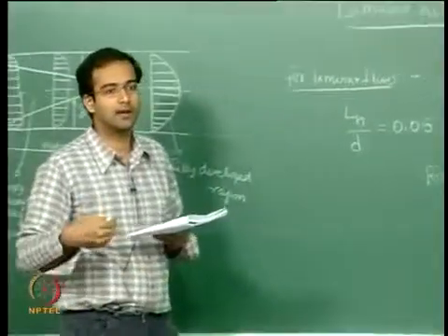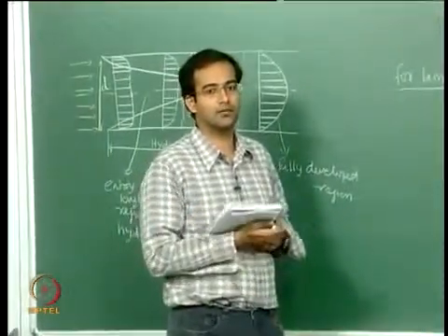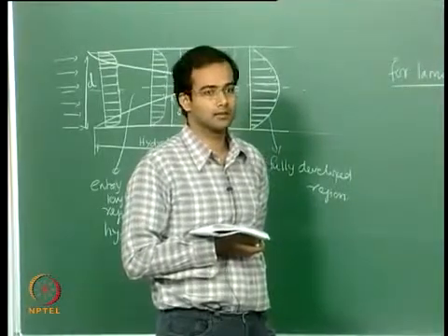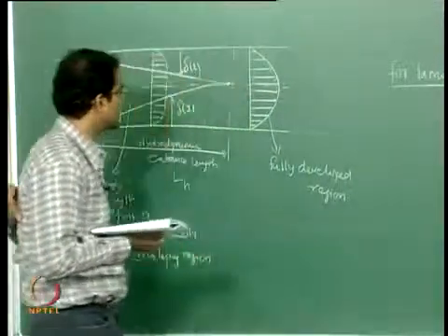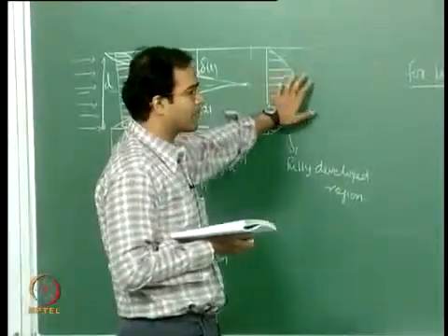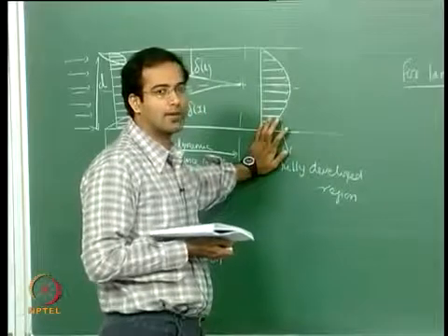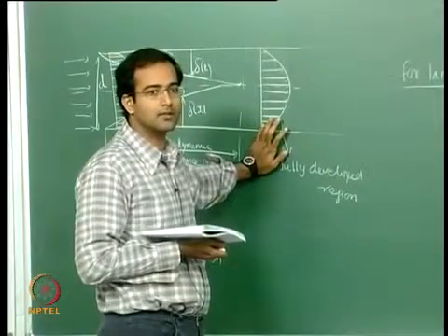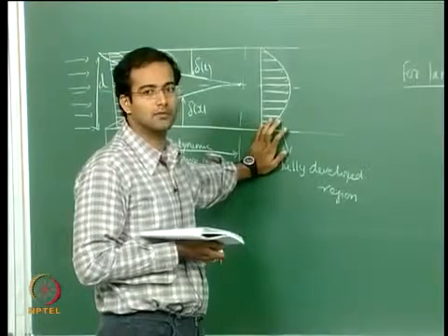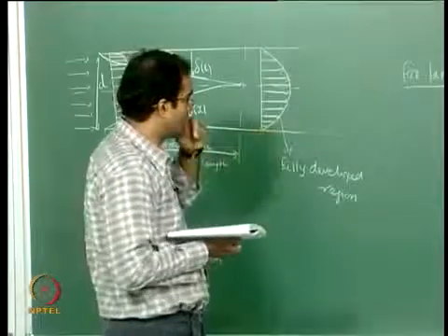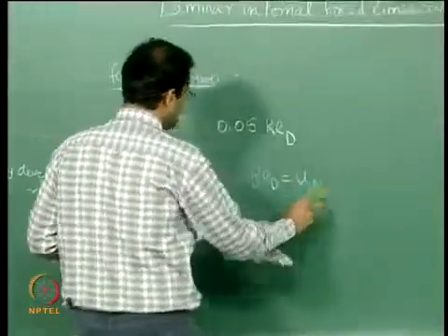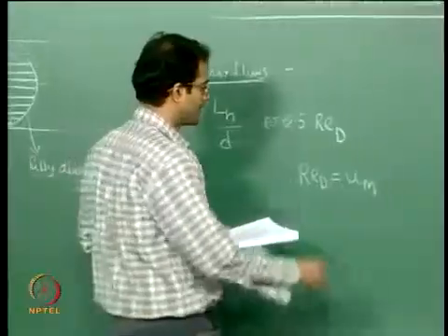so what kind of characteristic velocity do we have to use? That is the question. So the kind of an average, because here you see, even if you look at a fully developed case, you have a profile which is a function of y. Okay, so you don't have a fixed velocity value like in the case of external flow, like a free stream velocity. Therefore, you can use what is called a mean velocity, which we will define shortly. Okay, so this is your mean velocity.